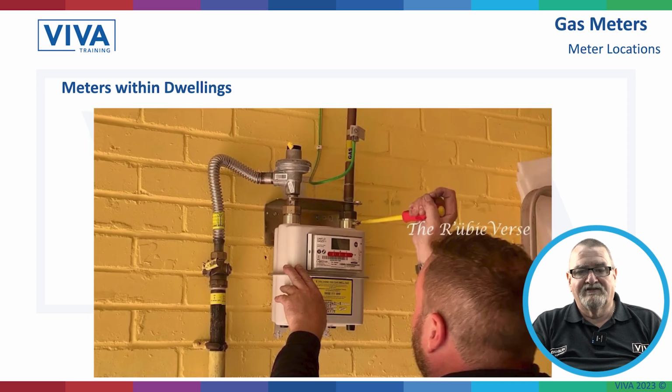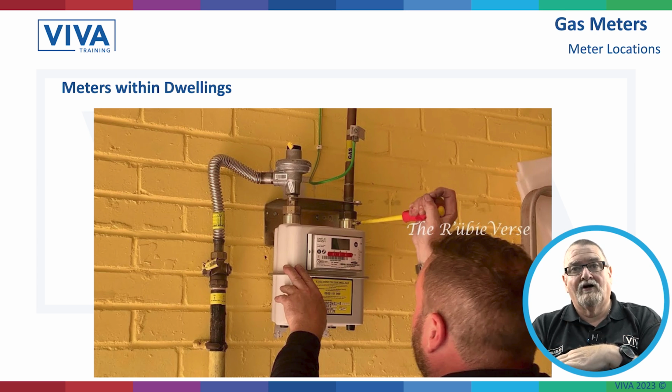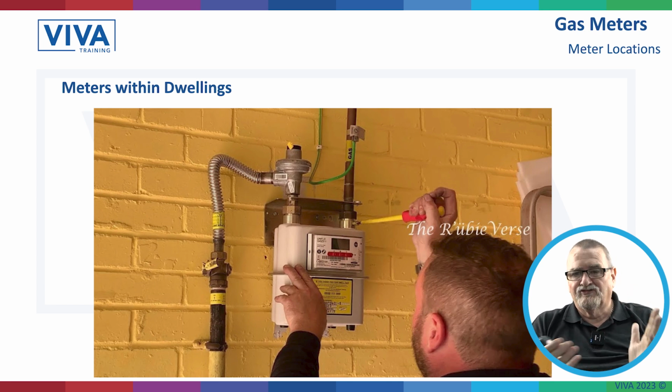So that's a gas meter fitted in a garage, and as we can see, we've got the ECV. Another thing that is worth mentioning is the on-off tape. The on-off tape's there to indicate to the customer which way the handle on the ECV needs to fall. It should always point upwards to on and then fall at 90 degrees to go off. It should never be the other way, fall into the on position, because if we shut it off, it shouldn't be that.